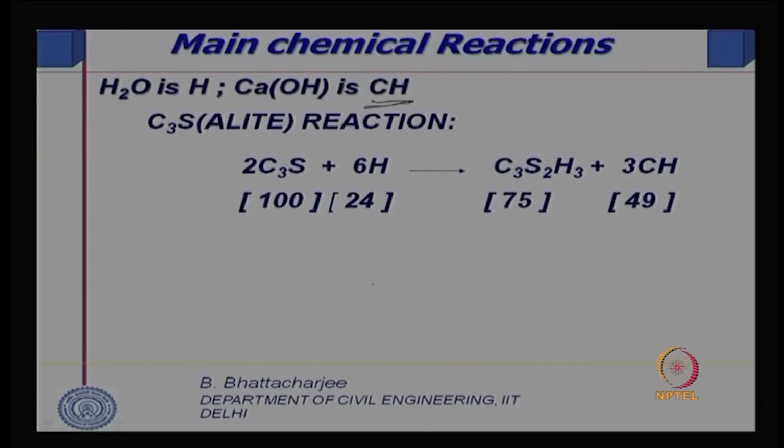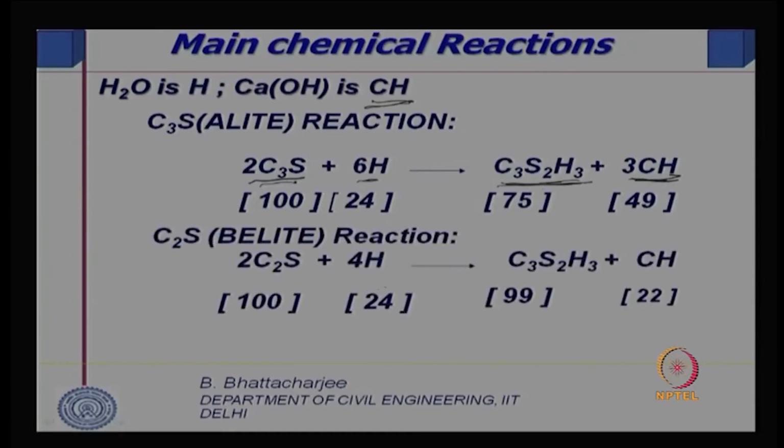So, 2 C3S reacts with 6 water, this is the typical reaction, forming calcium silicate hydrate, where the water goes into the calcium silicate structure, and calcium hydroxide.